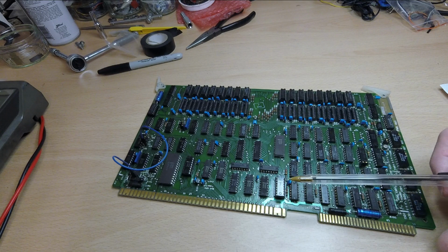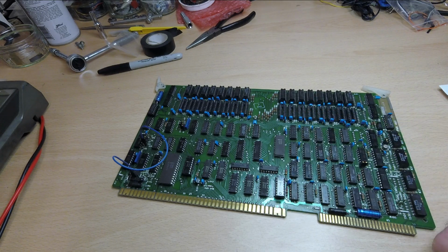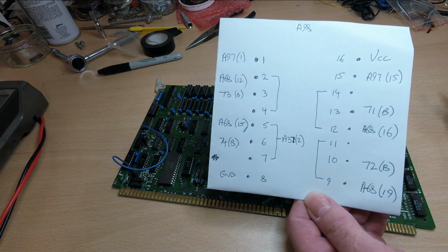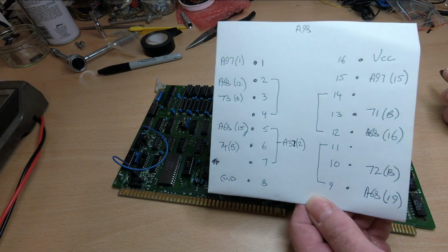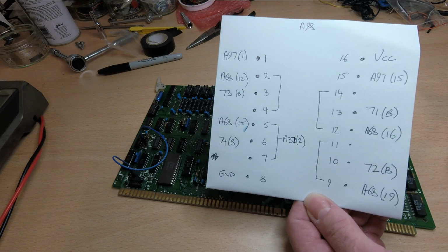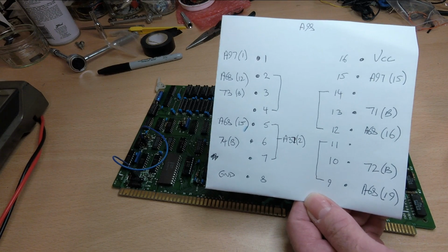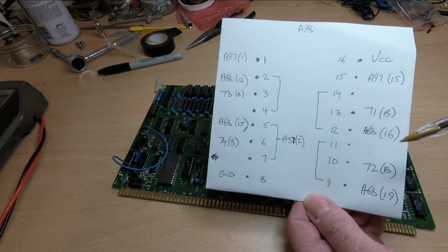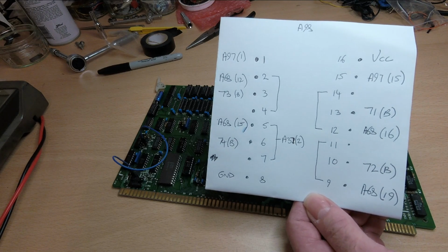If you are taking chips out of boards that are fairly old and sensitive like this, one little tip, just while I'm here, is to map out all the pins on the IC and where they go. Obviously you can do that from the schematic. There's a couple of reasons for that. One, the schematics, back when they were drawn, were done by hand, and there were often a few errors on them. And two, while you're extracting the IC, if you were to break any of the through plates or the tracks, if you don't know where they're going, you're going to have a really hard job putting them back again.